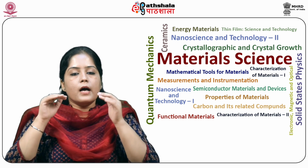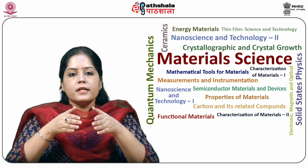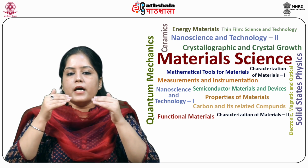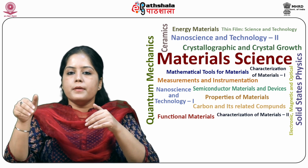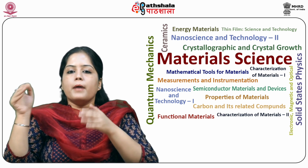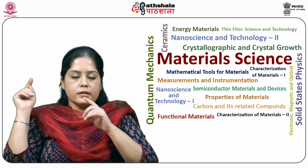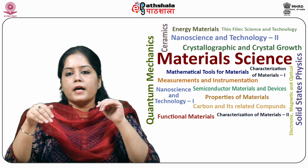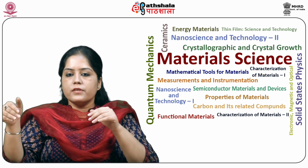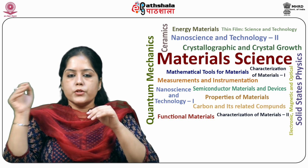Now therefore I_D is equal to I_P multiplied by V_D by V_P minus 2 by 3 multiplied by V_bi minus V_G plus V_D by V_P to the power 3 by 2 plus 2 by 3 multiplied by V_bi minus V_G divided by V_P to the power 3 by 2.